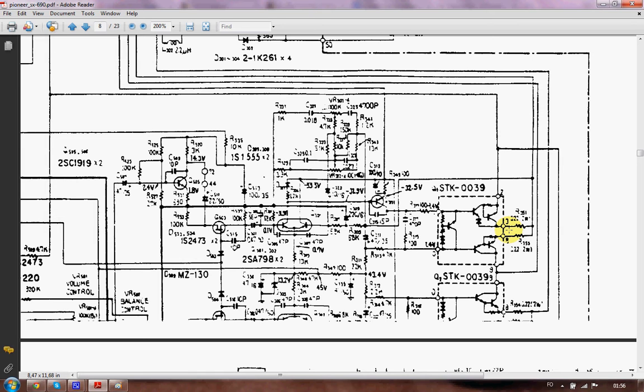So if there's something wrong with your amplifier, it will usually only affect one side, depending on how it's set up, of course. But in most cases, it's set up that way so that if something goes wrong and breaks the circuit of the amplifier, you're only going to lose one channel, and then you have the great opportunity to compare that channel to the other one.